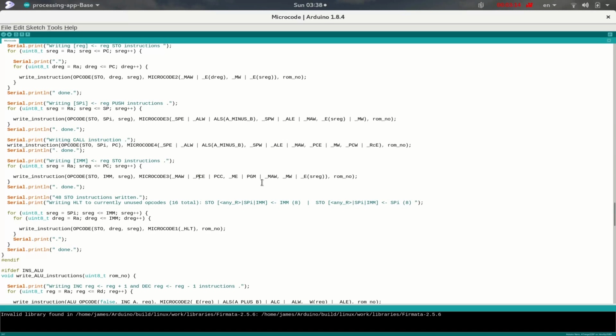And we then want to read out from program memory, so we enable the memory and we enable this program memory signal, and we want to read the contents, which are this immediate operand inside the program, directly into the memory address register, so that we can then in fact write into memory at that location.